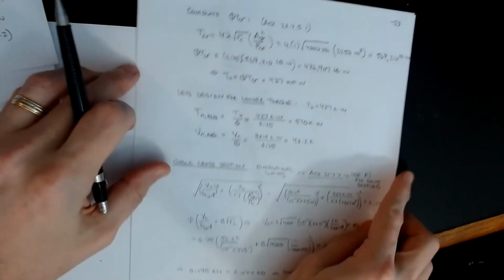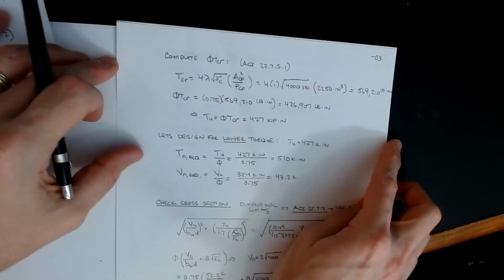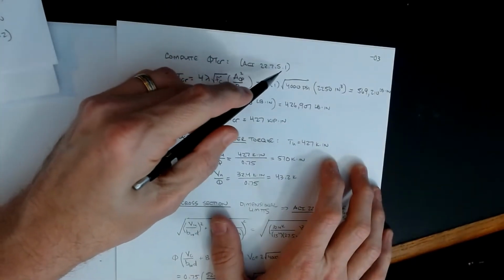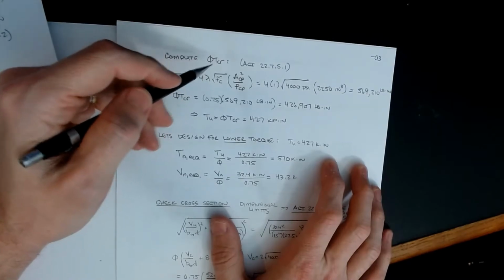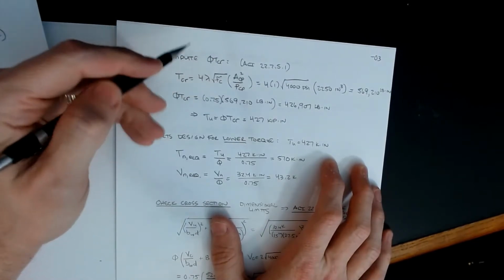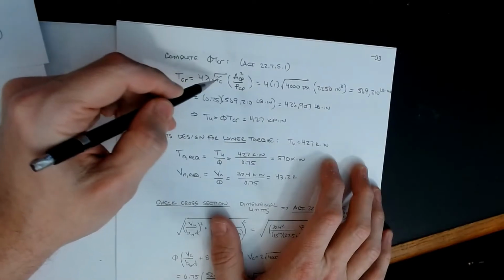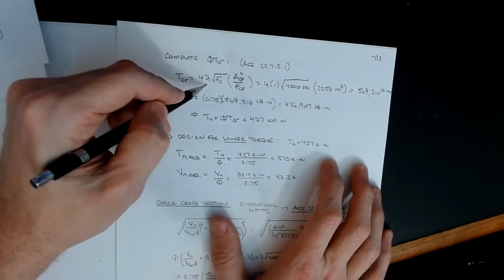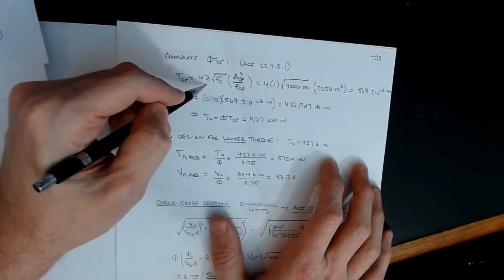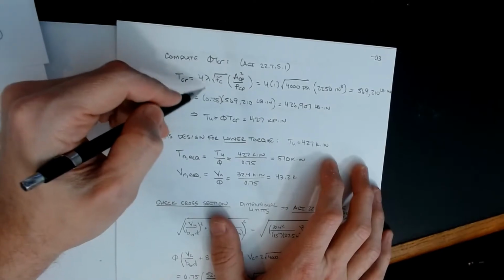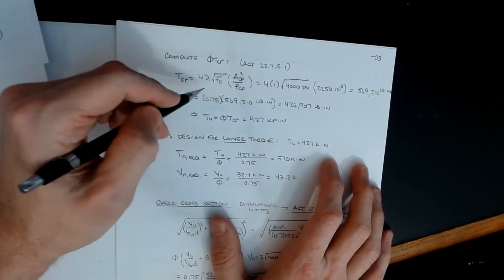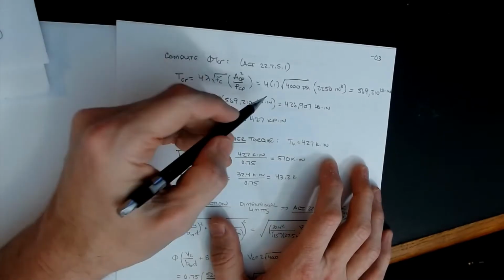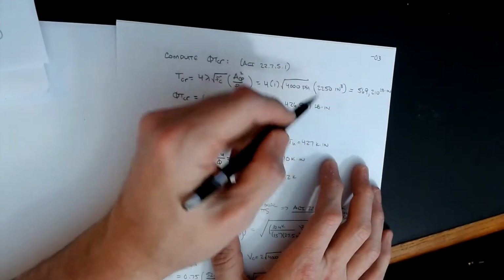Okay, all right. Oops, wrong page. Okay, so here we go. We're going to compute our cracking torque value. This comes out of 22.7.5.1. It's just the formula. T_cr, again, is 4 times the threshold value, or you can run the number. So we get 4 times lambda times square root of f'c times that A_cp squared over P_cp ratio. Lambda is the lightweight concrete coefficient. We're going to assume normal weight, so that's 1.0. If it's lightweight, you'll use the respective lightweight values out of the tables. But again, in this class, we're not going to do much with lightweight. So I plug the number in, 4 times 1 times square root of 4,000 times 2250. I get a number that is